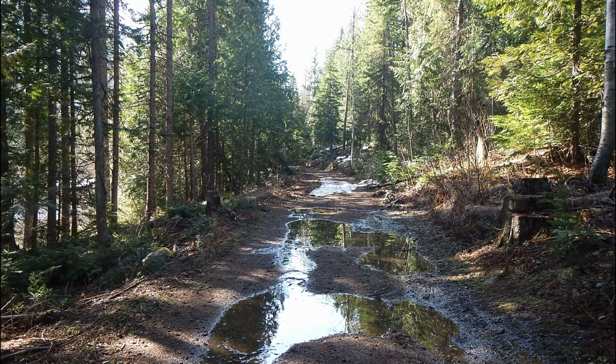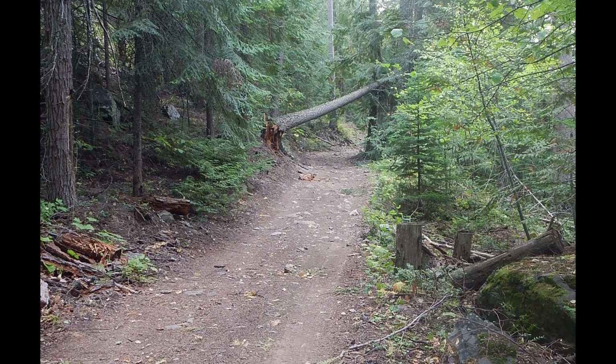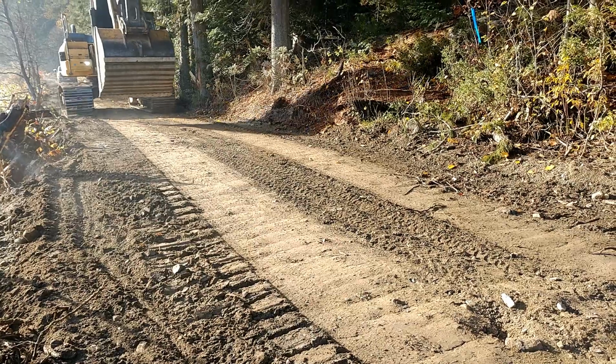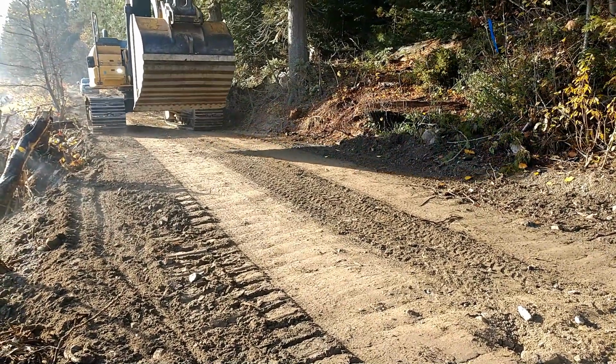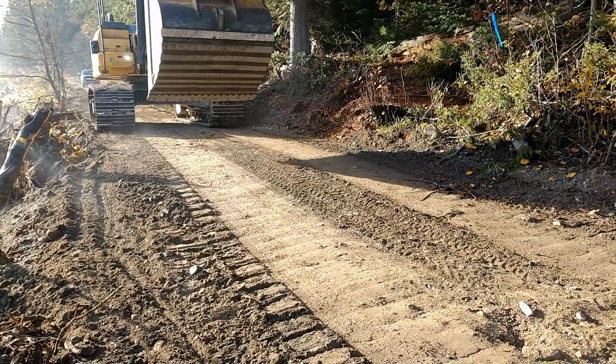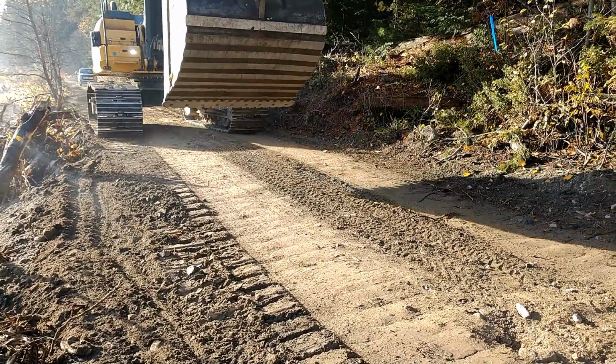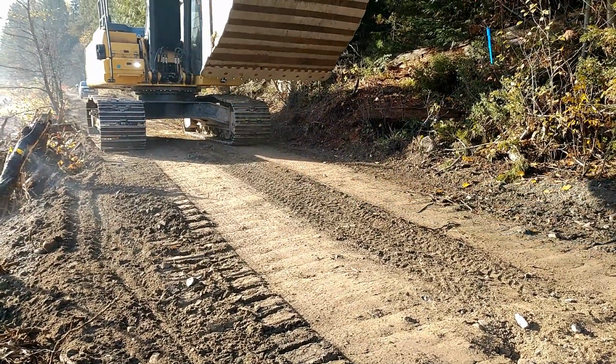The narrow mountain road leading to Violin Lake was rough, and it had wet areas where our vehicles could get stuck. The first step we took in construction was to improve the road so we could access Violin Lake without damaging our vehicles. The excavator and dozer operators removed trees and boulders, graded the road surface, and applied gravel so that large trucks could haul rock and wood slash to our work site.